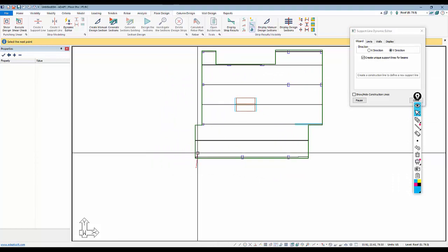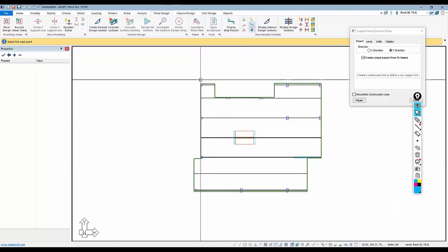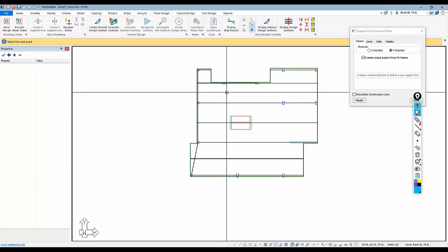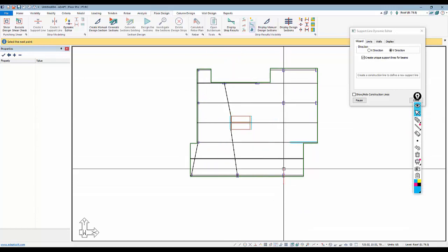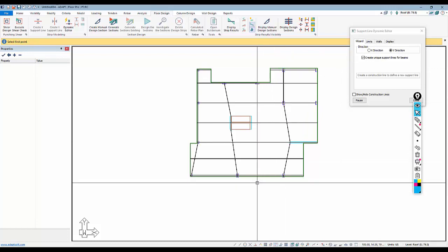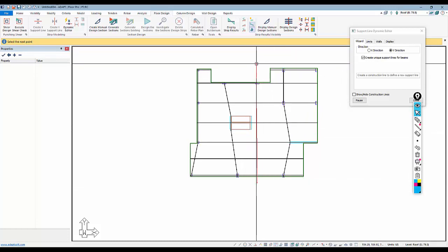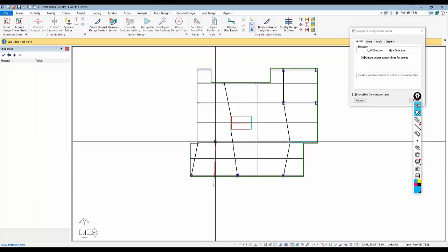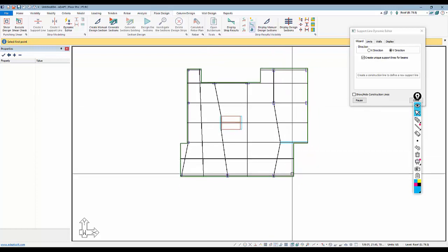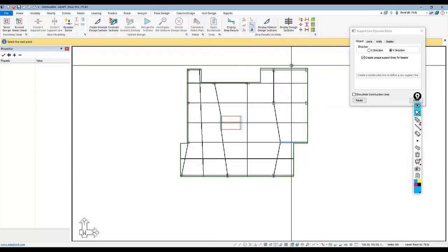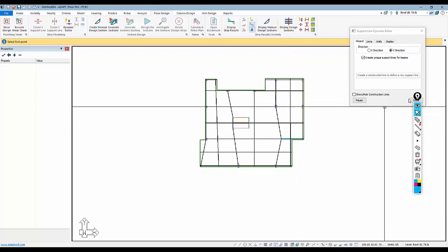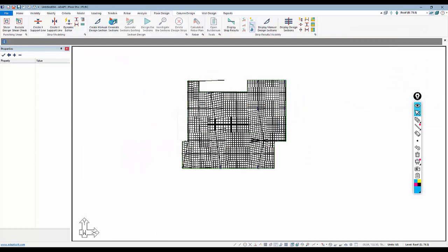And here, if I bend this line, I could actually create a continuous line there. I'm going to go up to this wall, something like that. I'll assume that's just a middle strip. I'll say that this is, there's a middle strip, and then just a middle strip there. Column strip on the outside. So something quick like that to generate the strips. I can go ahead and generate those.